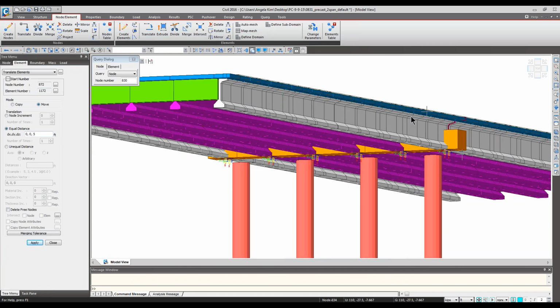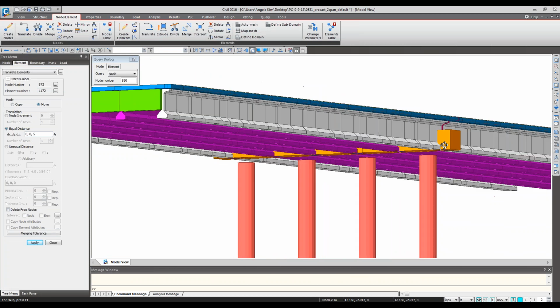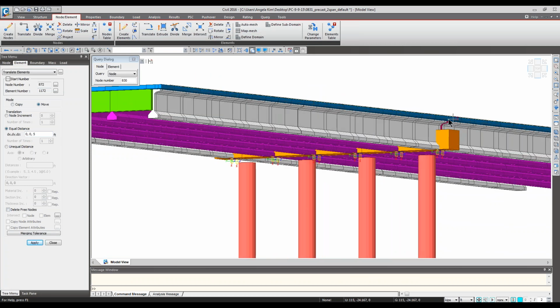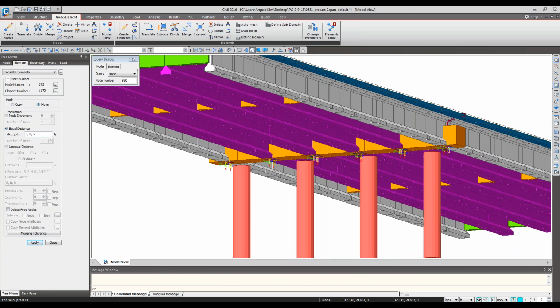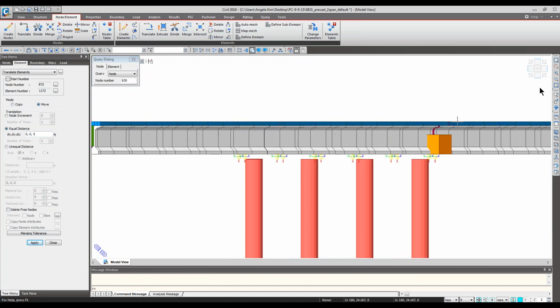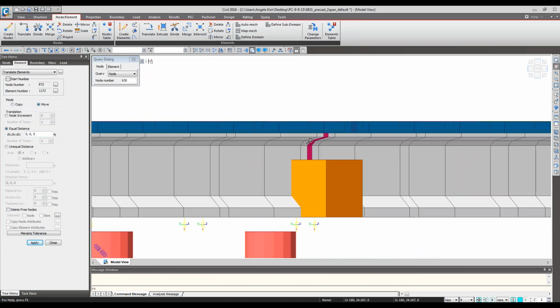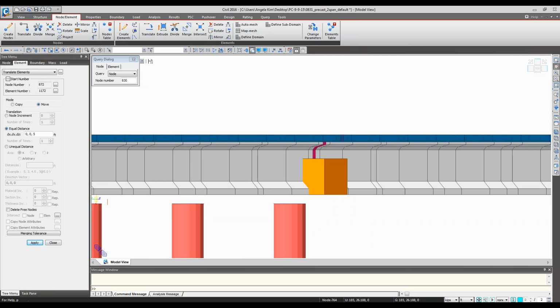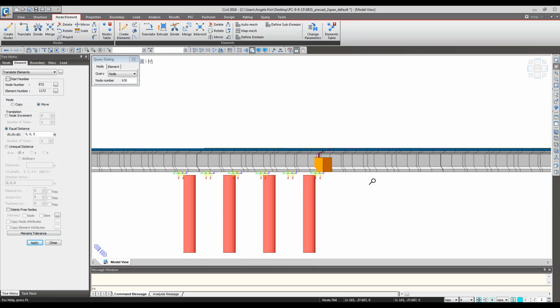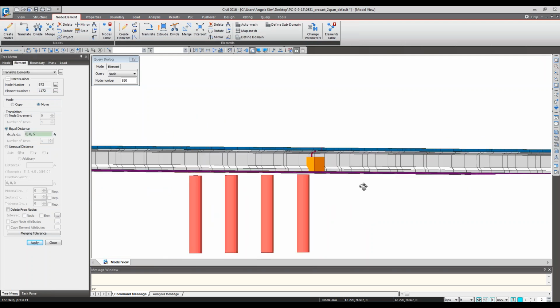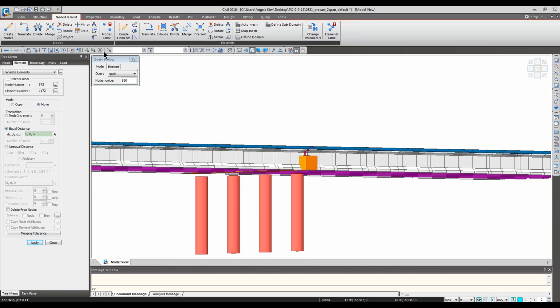And this may be coming down all the way from the deck, just poured once. You can actually reflect that by increasing the size of it. It's exactly the same way how we can change the section property right here. And this pier is now hanging in the air, but no worries. We can, of course, change the node coordinate for this pier cap too.